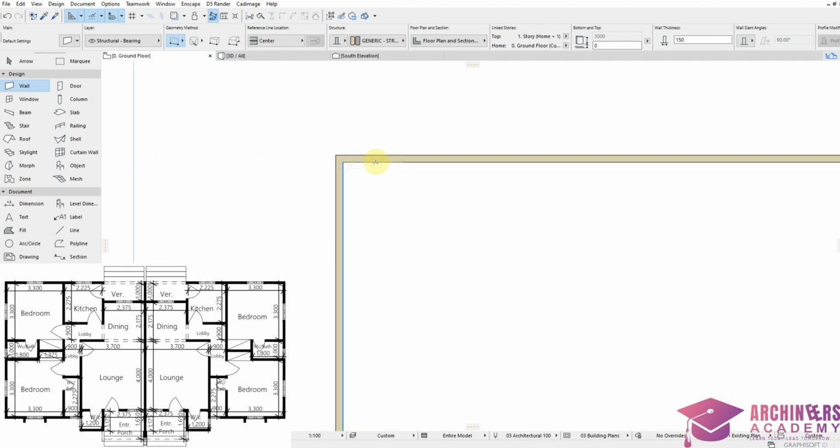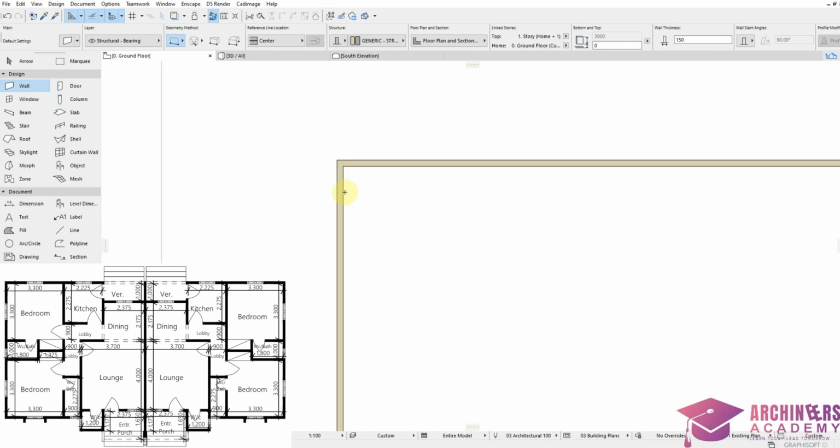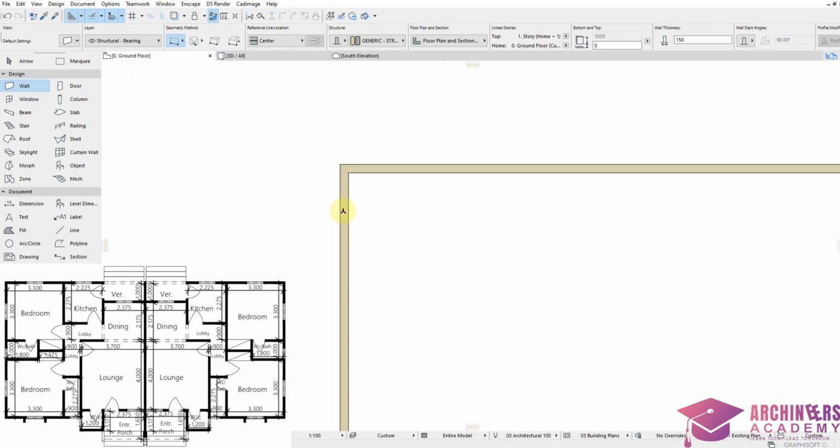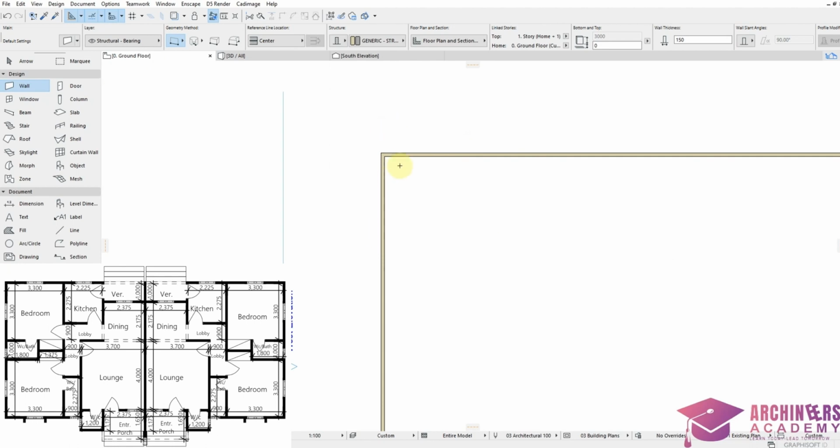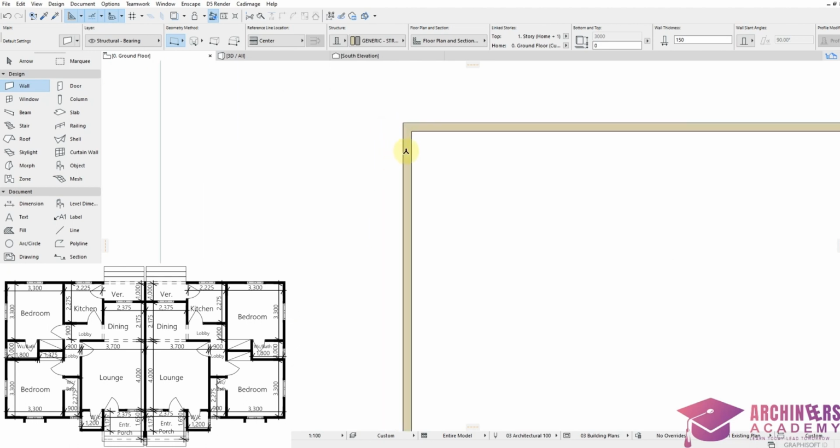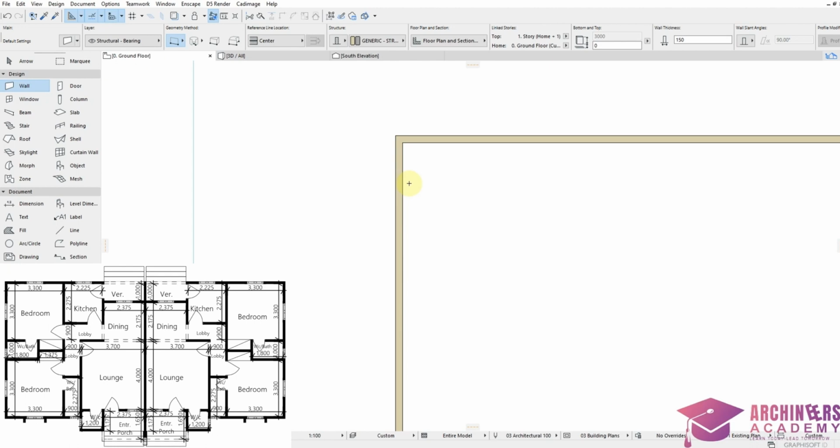I will not create another wall. I will not come right here and create another wall. No, if I need a vertical wall right here, I will duplicate this one. If I need a horizontal wall right here, I will duplicate these 2. Then the first thing we have at this angle, the left hand side, is the bedroom. So I'm drawing the semi-detached building, the apartment at my left hand side. That one I'm drawing first. Then we'll duplicate. Bedroom is 3,300 in dimension. 3,300.